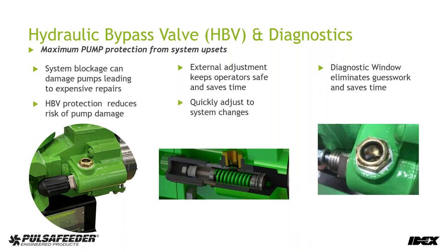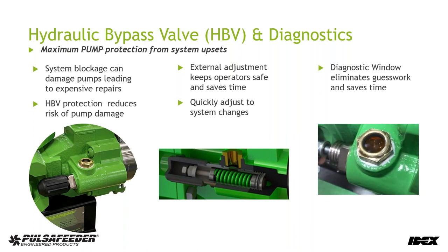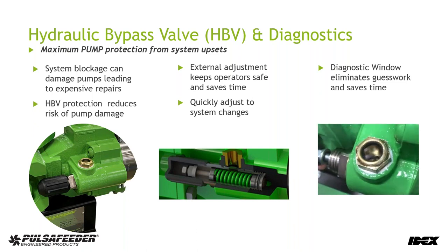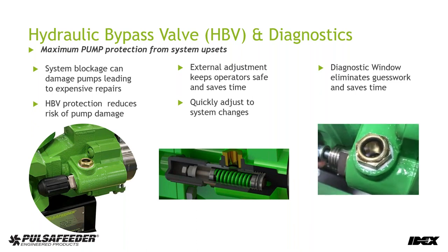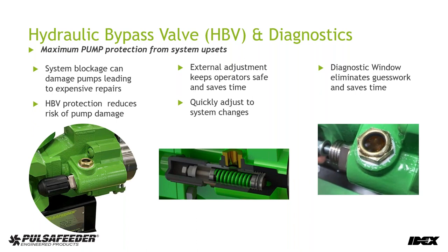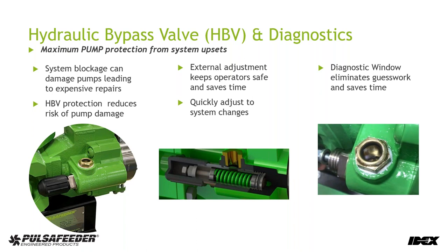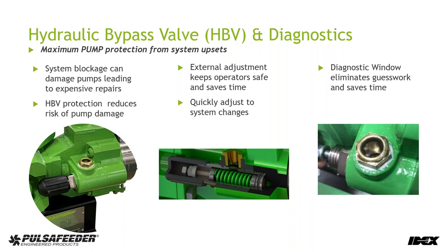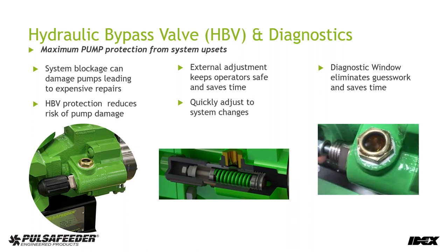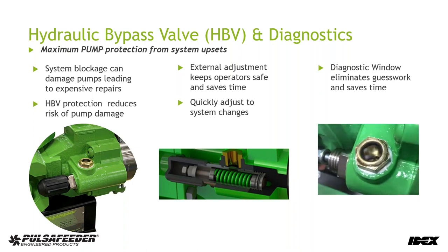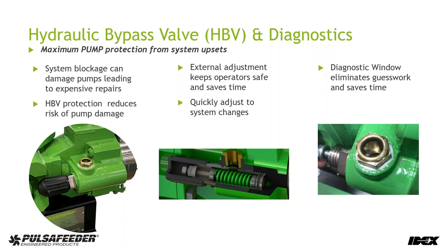So when you're troubleshooting, if you have a system problem, this gives you a real quick indication of whether or not this pump is the problem or I need to look someplace else. So it saves you time in troubleshooting and evaluating system status. That diagnostic window is a key element that eliminates guesswork and saves you time.